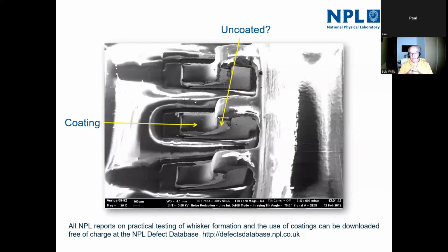Now, I mentioned tin whiskers, and really the growth of conformal coating has significantly increased because of the issue of tin whiskers. For those of you who are not familiar, it's a problem that was highlighted with tin finish, when the industry went to tin finish on component terminations, on PCB substrates, and also on RF shields and things like that. The plating process, if not properly defined and controlled, could actually create tin whiskers.